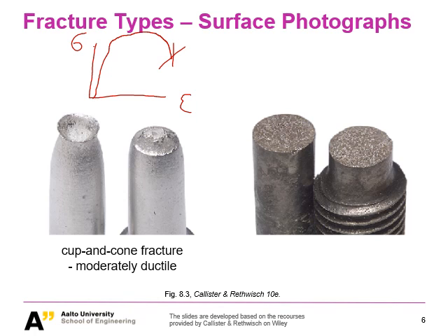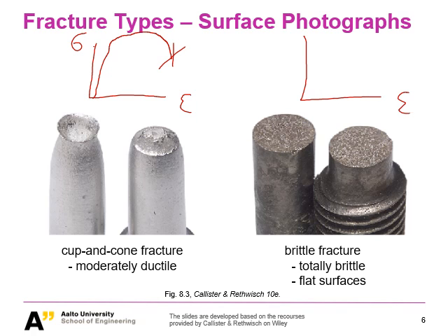And on the other hand, you can see this is the typical brittle fracture. A very important characteristic of the brittle fracture is it has very flat fracture surfaces. You can see there's no cup and cone. If you also try to see what it looks like in terms of the stress strain curve, you probably remember it usually goes like this, and then boom, fracture.